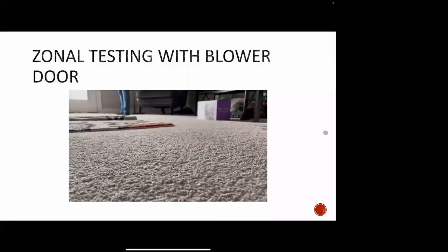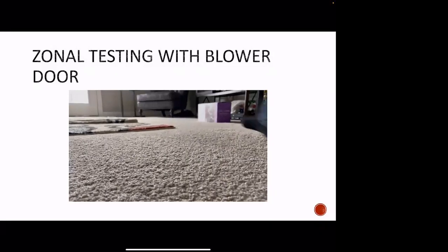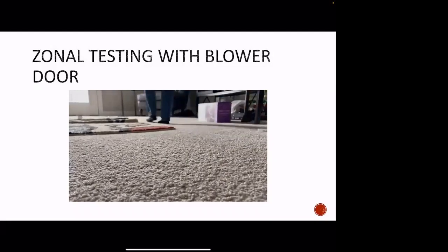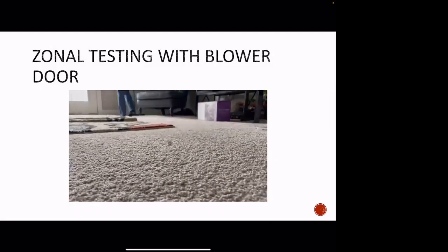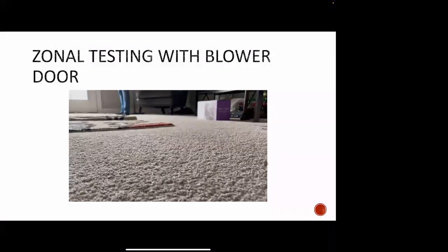So what's actually happening is I have that blower door depressurizing the house, which is pulling in and just exposing all that air leakage. And with that air leakage there, it's actually sucking out on the bottom plate underneath the carpet and lifting this carpet up. We need to be aware of that. We need to be concerned with that.